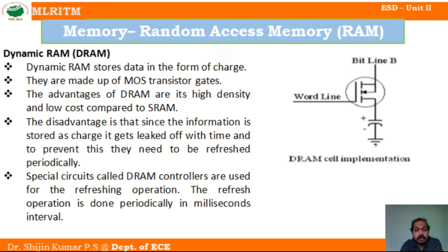It has a disadvantage also. Since the bits are saved as charge, it will get leaked off with time. To prevent this, we need to refresh it periodically. The refreshing process is required, so for that purpose an additional refreshing circuit is required. That is one disadvantage of this DRAM or dynamic RAM.